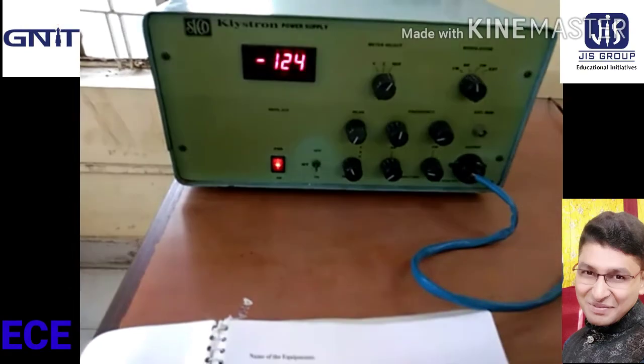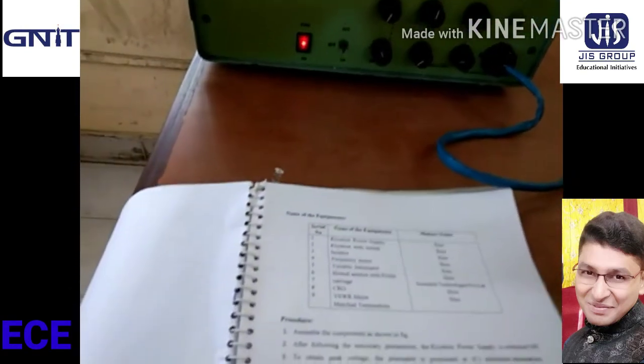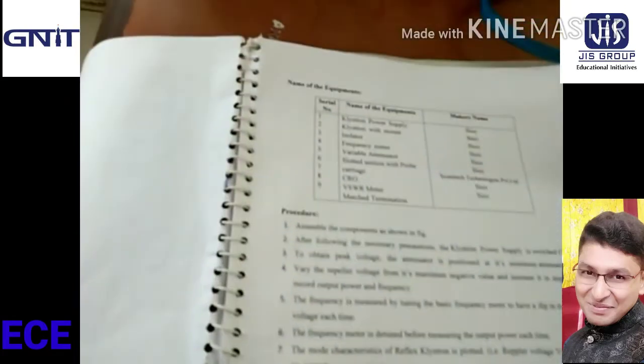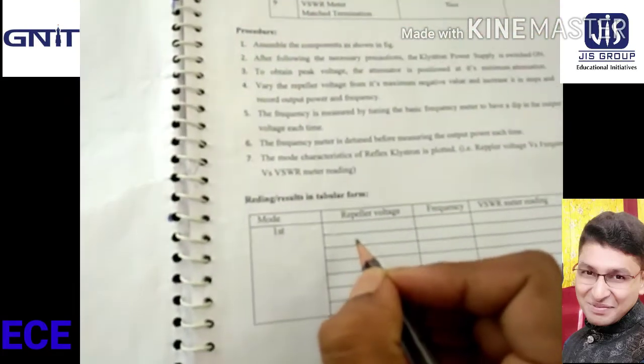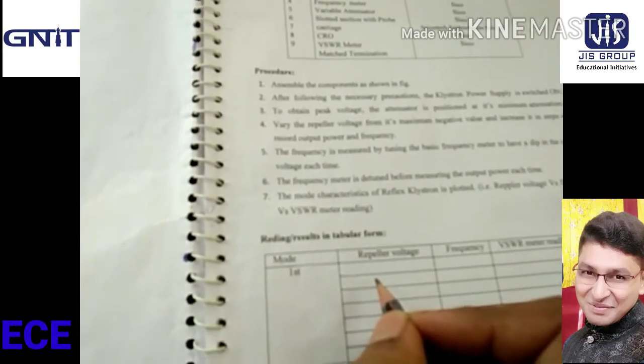This is the midpoint, the maximum peak voltage. Note down the repeller voltage: 124 volt.